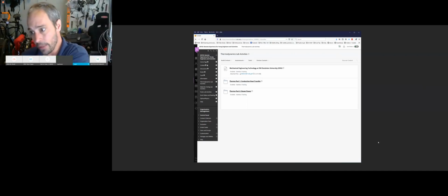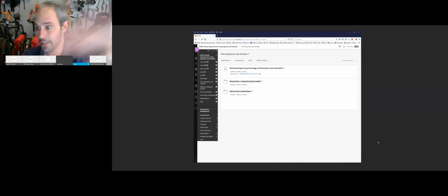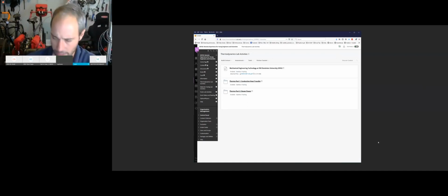So what we do is we're now pulling energy out of the cool space and kicking it to the outside. Now, in an air conditioning unit, the cool space is your house, and where you're kicking the energy is the outside. So the condenser unit, all that's outside. If you have a refrigerator, it's the refrigerator space and the freezer space. Basically the same concept. Now, a heat pump is the same concept as well, but with a different desired output. For a refrigerator and air conditioner, the desired output is the heat removed from the space, the energy removed. So either your house or the refrigerator. If it's a refrigerator, you're kicking that heat into the house. If it's an air conditioner, you're kicking the heat to the outside.